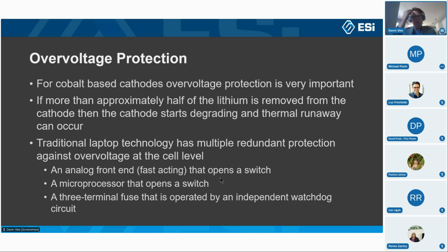If the charger were to provide excess voltage, or if you had a severe imbalance in the voltage in the cells, such that the charger cannot tell that, say 12.6 volts in a 3 series battery, well, we've got one cell at 3 volts and one cell at 4.5 volts in that 3 series battery, and now we're going to just keep charging.